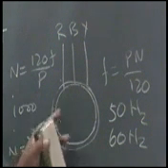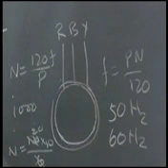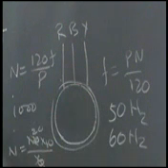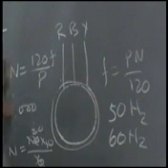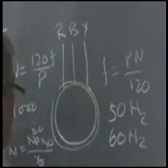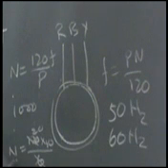So what is this N? It exists only for the RPM of the rotating magnetic field. Otherwise, it is not existing anywhere. So this is the first interesting fact about the induction motor. This is called the synchronous speed. This is the speed at which the magnetic field rotates.